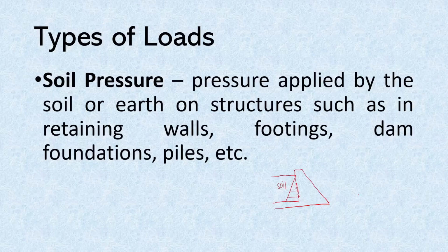And then for footings, let's say we have this footing, and then we have our column, and then usually loads are transmitted to the columns. So let's say we have this one. Our footing stands on soil, and so the soil will have a uniformly distributed reaction throughout the span of the footing. So let's say the soil will react this way. The soil is just essentially a support that has a uniformly distributed reaction.